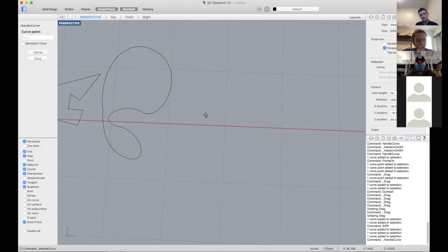So when you begin your drawing, you typically want to start on an axis. The way you do that is when you start your control point, anytime you're doing anything, if you want to go in one of the axes orthogonally, then you hold shift and it locks to any of the axes. If I'm starting a complicated curve, I'll start on an axis. That way I remember that I started on that axis and I can meet right back up with it. And then you can rotate it if you don't want to keep it in that orientation. So yeah, you can start it on an axis.